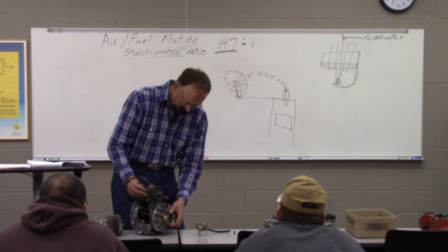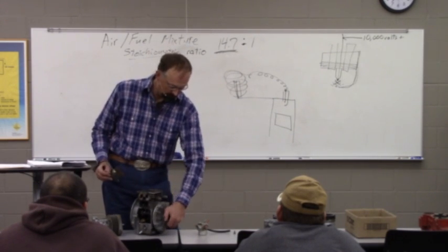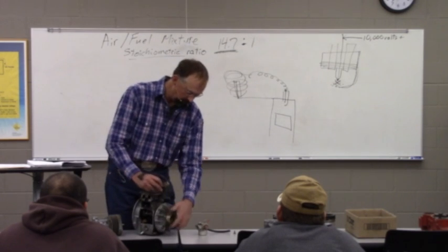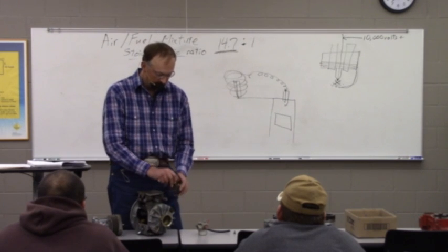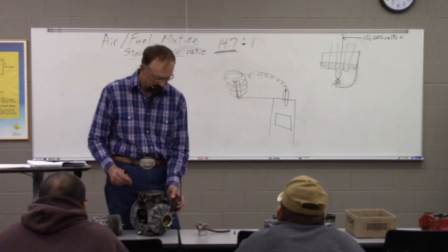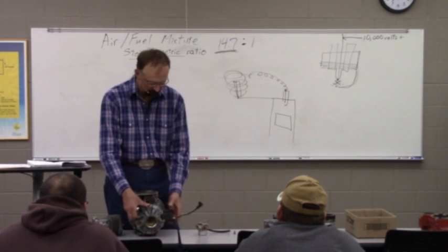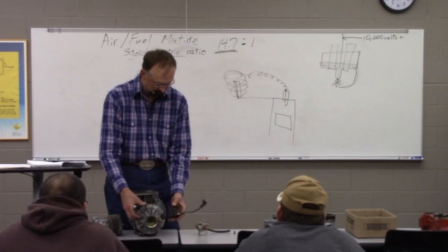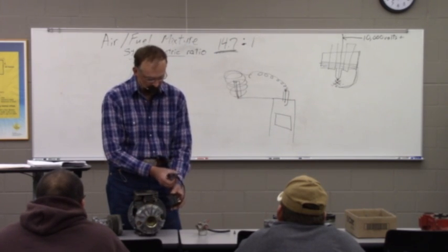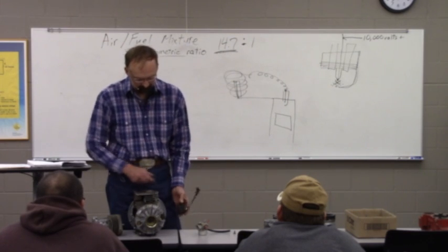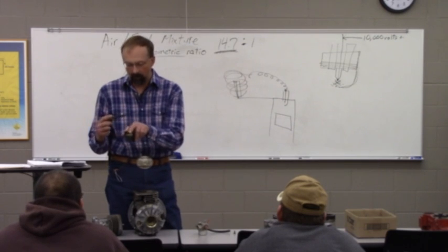But anyways, what's done is right when they want the spark happening, as far as where the rotation of the engine is, that's where they put the permanent magnet on the flywheel. So that right when it passes by here, and you can actually feel it, see the magnetic field is holding it on there right now. But if you really wanted a jolt, why, hook up to this and we'll pass it by there, and there'll be a pretty good electrical pulse coming out this wire.